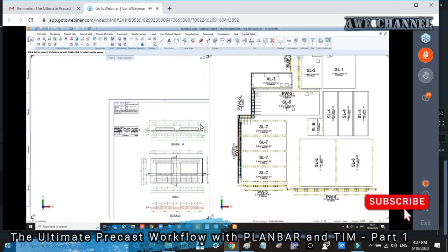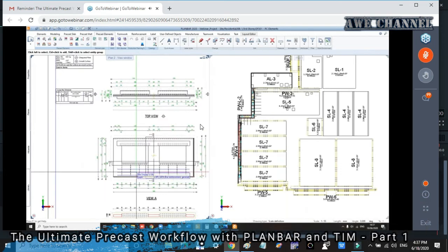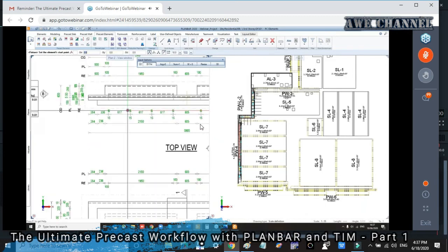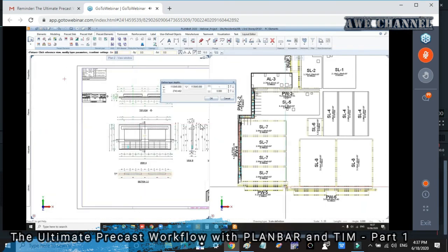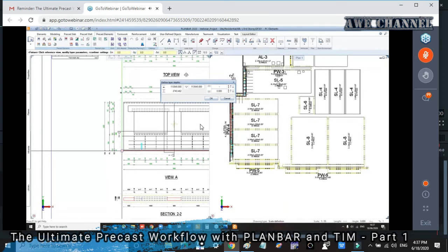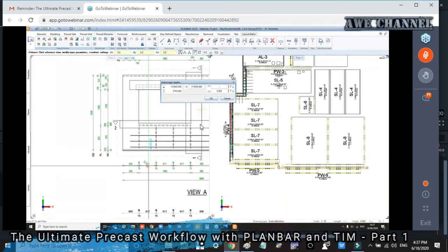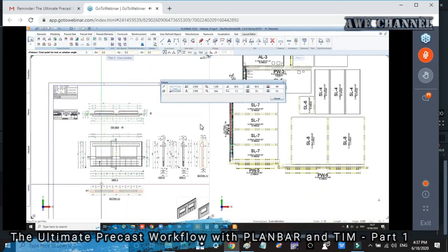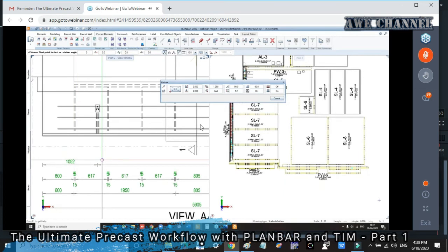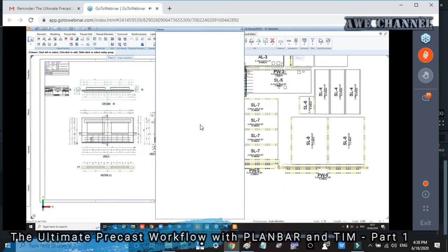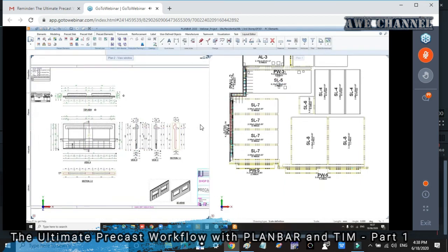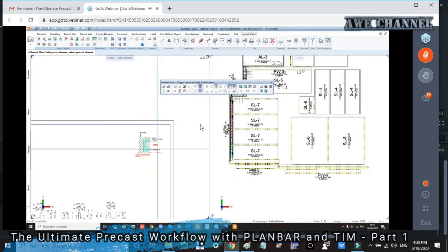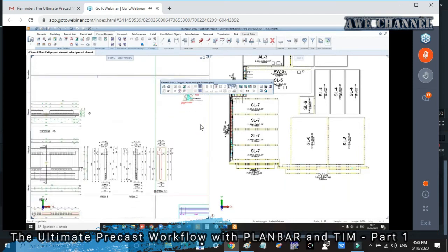detail. So let's say for example I'm going to put the splice sleeve, so maybe this one somewhere here, and place there, so I can say okay, and it automatically adopts the dimension. As you can see from there, it becomes 152, and we can update again the element plan, and you should have your detail coming out from there.